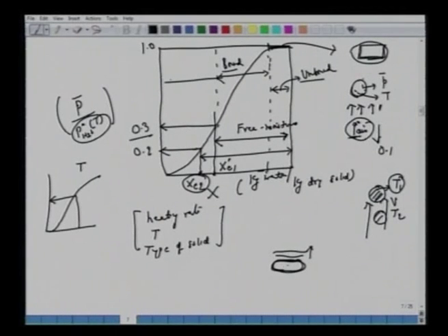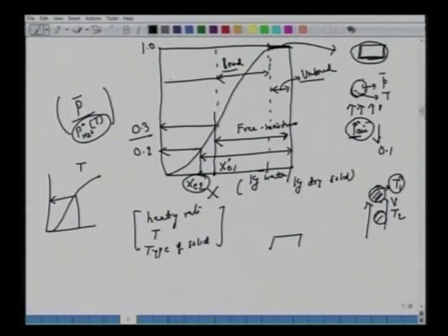Below this, now we are talking of dry patches. Okay. So what we are saying here is that, to begin with, the solid has a film of water over it. So the partial pressure is the same as the partial pressure of pure water, and then patches of dry surface start appearing, and then we have a different type of moisture, which we call bound moisture. Okay, so we use three terminologies here. One is free moisture.